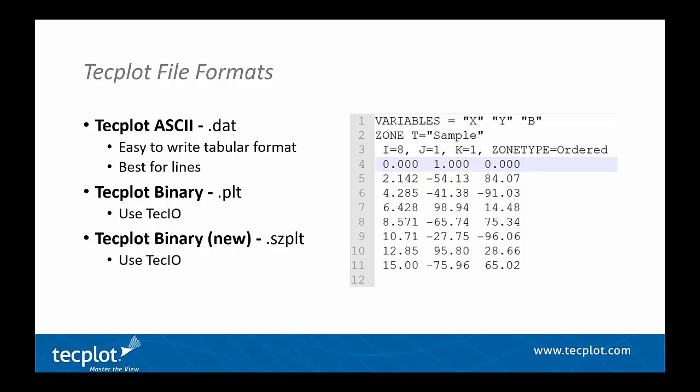On the more complex side, you will get the Tecplot binary formats. .plt and .szplt are our 2 formats. PLT is kind of the industry standard. It's been around for many years and is written and read by many different products in the industry. Our newer format, .szplt, is what we're going to be concentrating on today. We're trying to push this one because it's a lot faster to read into Tecplot 360. And TecIO can both read and write szplt.